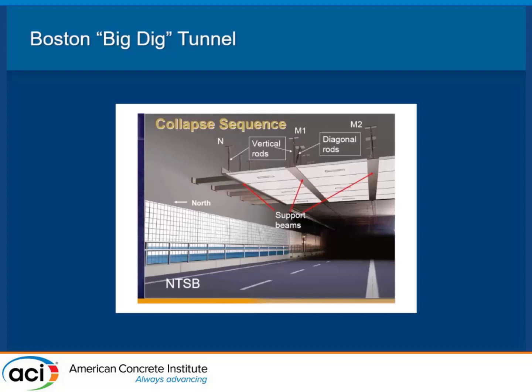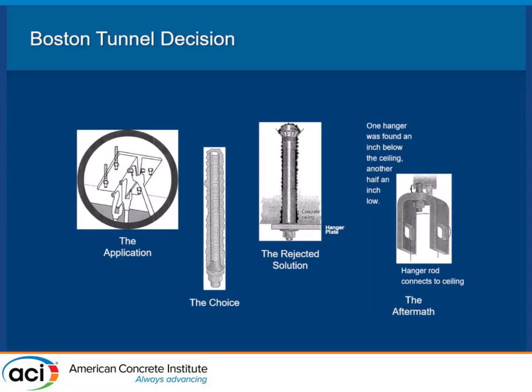Not all the Boston tunnels used the adhesive anchors. Many used channel anchors. In the D Street portal, the ceiling was installed in 1999-2000, well after the cut and cover tunnel was constructed. Ceiling panels had to be designed to accommodate suction load of about 45 psf. The anchor service load was on the order of 2,600 pounds. These are the general conditions, sketches of what was installed to support the ceiling of the plenum. As you can see, that was the typical detail.